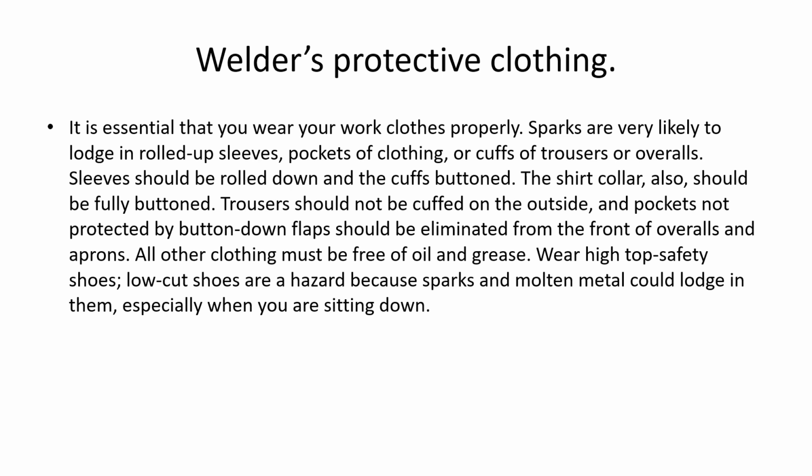Welder's protective clothing. It is essential that you wear your work clothes properly. Sparks are very likely to lodge in rolled up sleeves, pockets of clothing, or cuffs of trousers or overalls. Sleeves should be rolled down and the cuffs buttoned. The shirt collar also should be fully buttoned. Trousers should not be cuffed on the outside, and pockets not protected by button down flaps should be eliminated from the front of overalls and aprons. All other clothing must be free of oil and grease. Wear high top safety shoes.